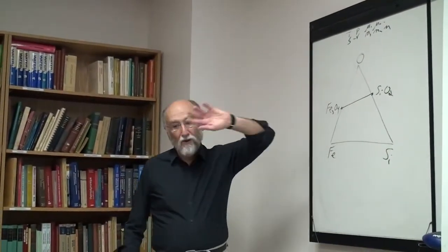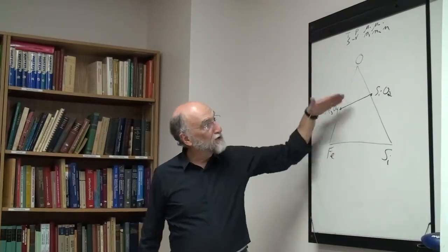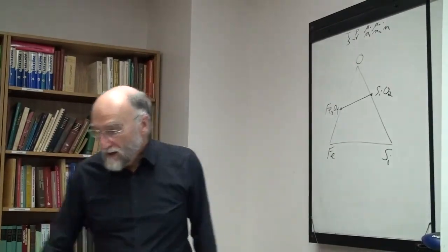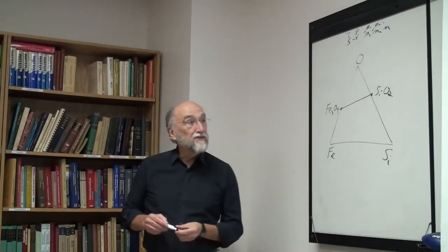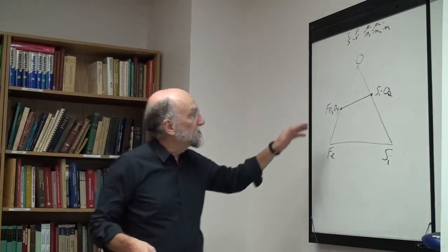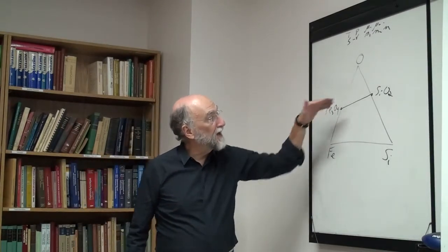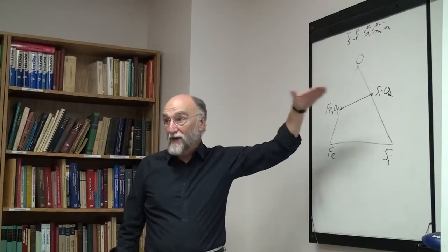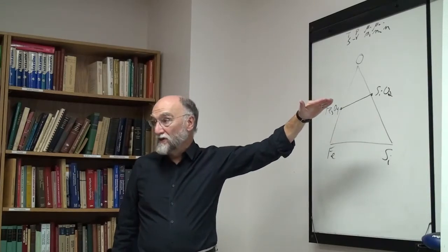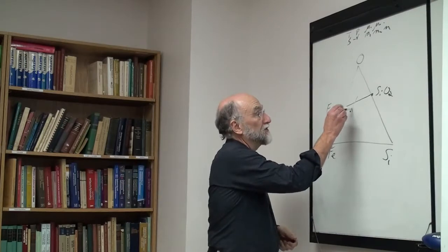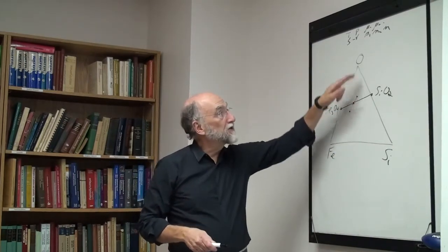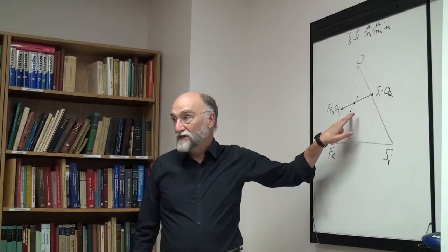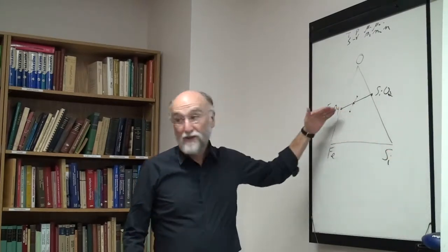This is simply an isoplethal section, just like we showed earlier where you had three metals, magnesium, aluminum, silicon. You're taking an isoplethal section and cutting across it. In certain cases, like when we had calcium, oxygen, silica, the calcium silica system would be an actual quasi-binary section because all tie lines lie along it. In this case, it isn't. You can have an overall composition here, but the tie lines can be on different ends. One phase could have more oxygen and the other phase could have less oxygen. This is simply the overall composition.